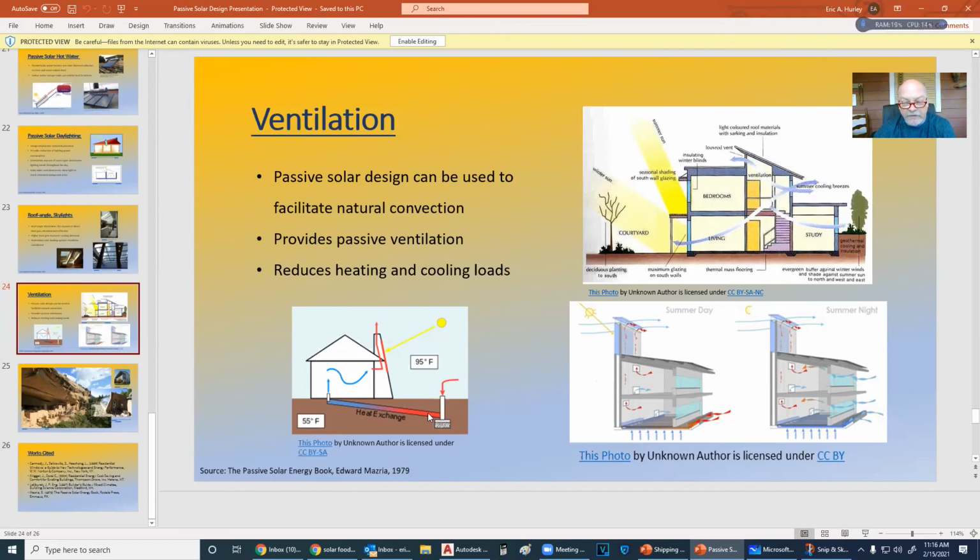And in this fashion, my concern is condensation in this tube, because at some point, again, with the psychrometric chart, 95-degree air in Western North Carolina is generally about 80-90% humidity, and when we pull it into a cool environment, we're going to end up having water condensate in here.